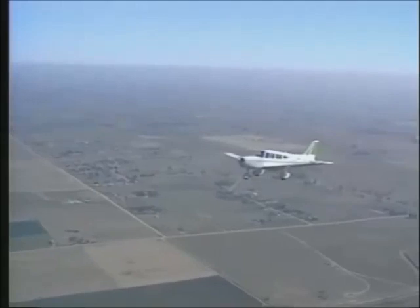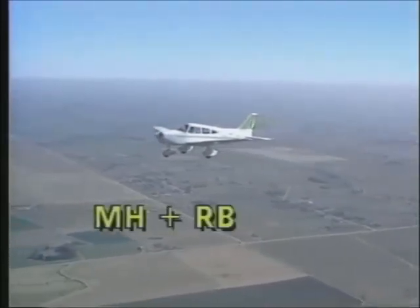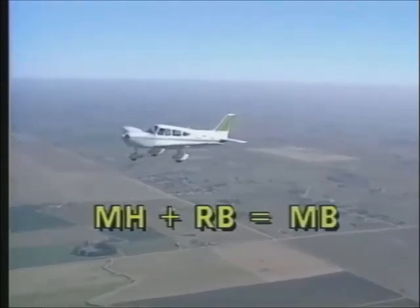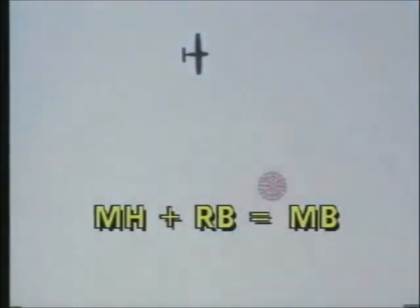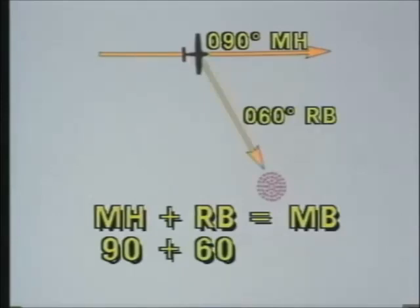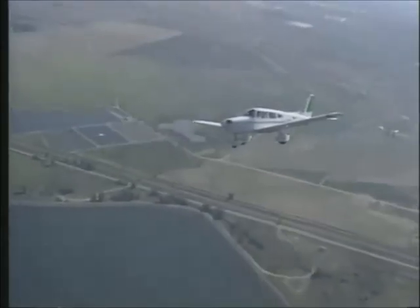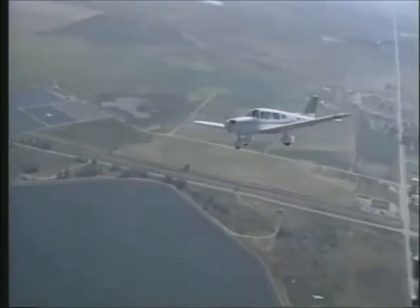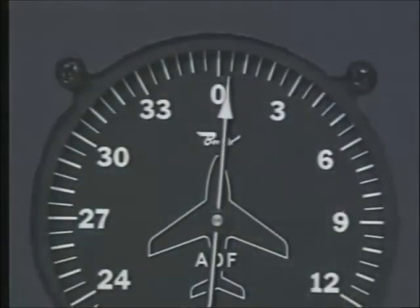If you're flying a magnetic heading other than north, you must add your magnetic heading to the relative bearing to find the magnetic bearing which will take you to the station. For example, let's assume your magnetic heading is 090 and your relative bearing is 060. When you add these two together, you get a magnetic bearing to the station of 150 degrees. To fly to the station, in this case, you simply turn to a heading of 150 degrees. When the turn is complete, the needle on the bearing indicator will point to 0 degrees.